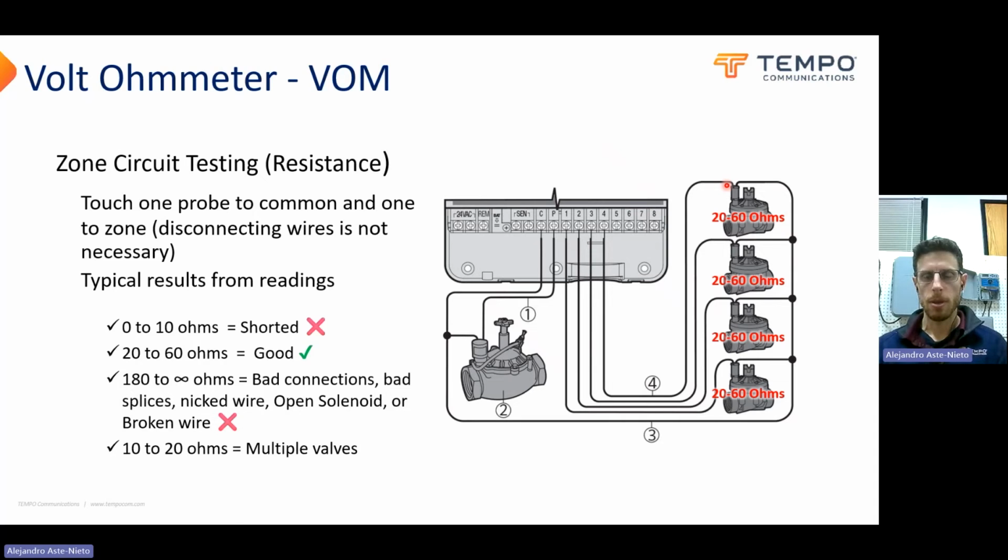Same goes with wires, but even 18 gauge wire might be, I think, like 8 to 10 ohms of resistance over 1,000 feet. I forget the numbers, I'll have to check, but 12 gauge wire is like 2 ohms over 1,000 feet.